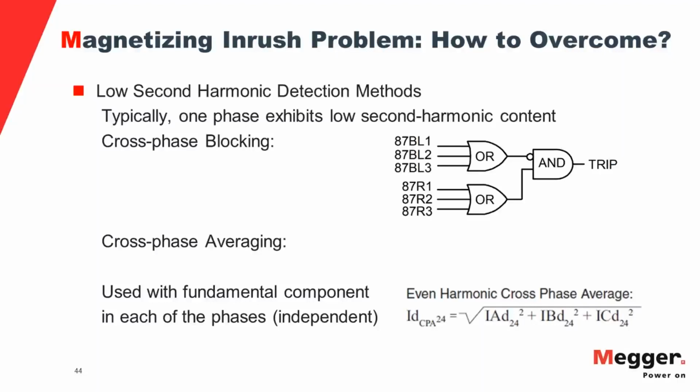The second abnormal condition, which is quite popular, is over-excitation. What exactly is it? It is nothing but overfluxing in the transformer. By overfluxing, it means excessive volts per hertz. So if volts per hertz on the secondary side goes greater than 1.05, according to the ANSI C37 standard, on full load conditions, then there is a condition of overexcitation.